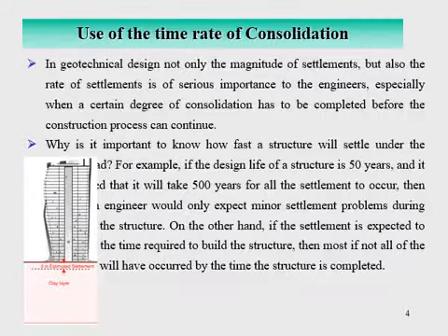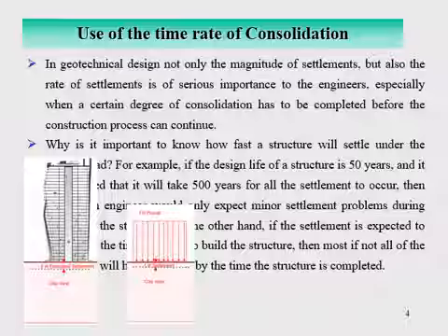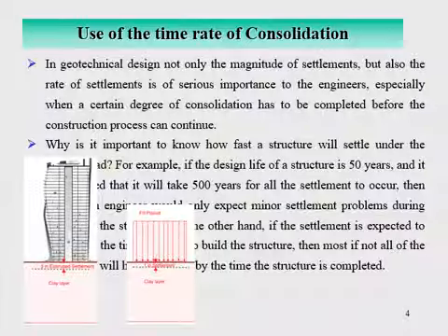And you say this is huge settlement. So what you do, for example, before the construction of the building, you place some fill material on this site, and let this fill material be there.